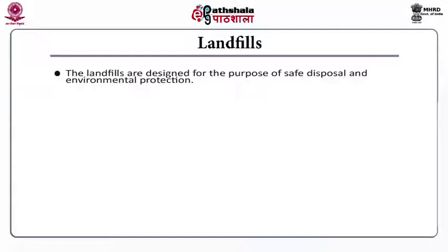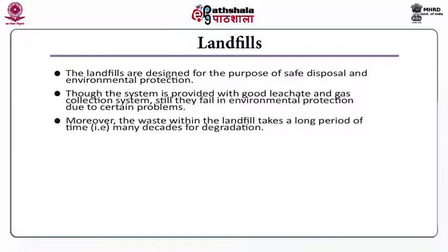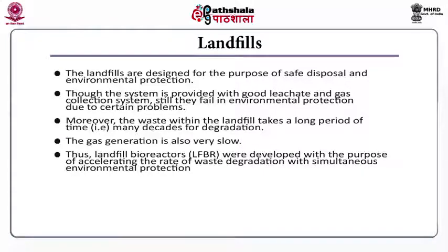Generally, landfills are designed for the purpose of safe disposal and environmental protection. Though you take steps to control the leachate or provide a gas collection system, still they fail and cause environmental damage. Moreover, the rate of waste degradation inside the landfills is very slow. It takes many decades for degradation. Also, the gas generation is very slow. Thus, the concept of landfill bioreactors was developed with a purpose to accelerate the rate of waste degradation with simultaneous environmental protection.